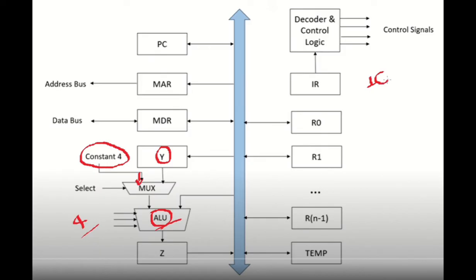Let's consider that the ALU can perform 16 operations, like add or subtract. These 16 operations can be controlled either by 16 control lines, one for each operation, or we can encode them so that they have 4 control lines, as shown. In that case, each combination of these 4 control signals selects one of the operations as the output.